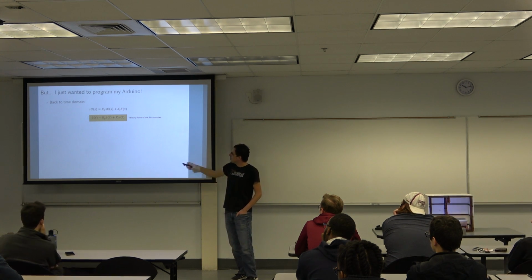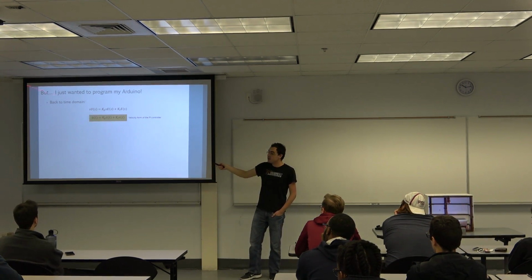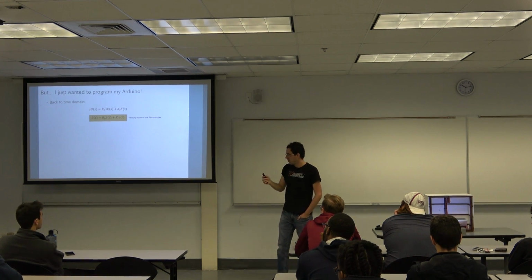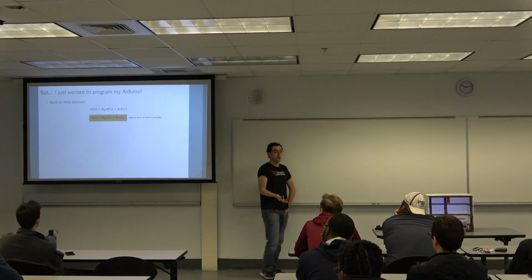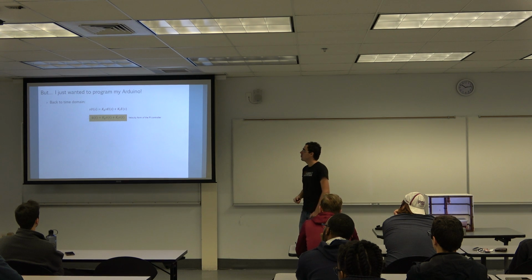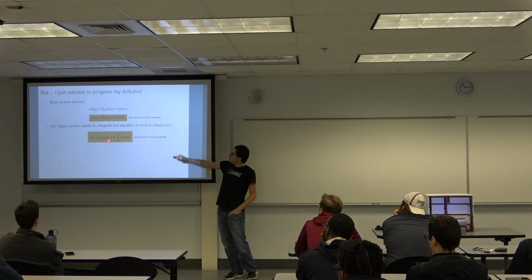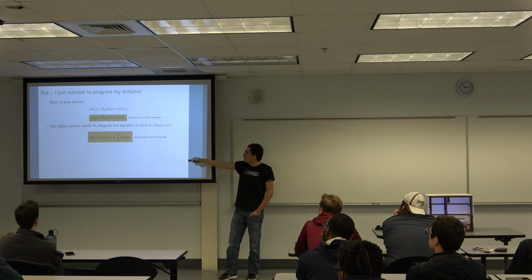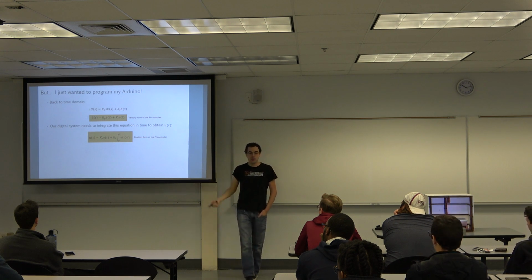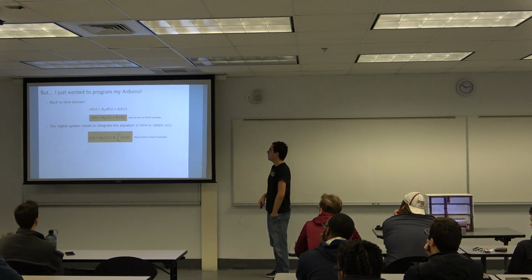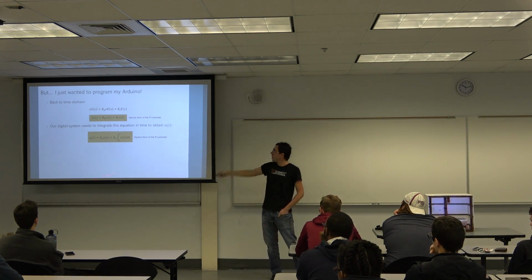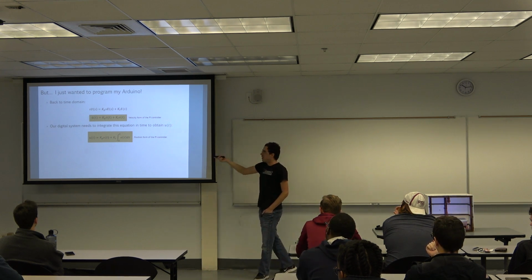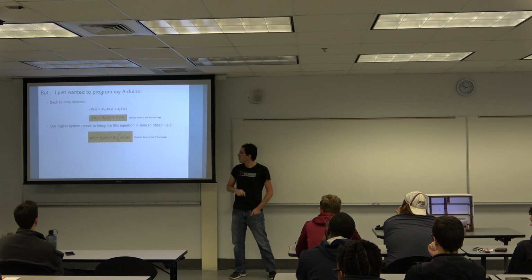And it computes the derivative of the control input. But most of the time we're not too interested in the derivative of the control input. We're actually interested in the control input itself. So we need to integrate this once. So we integrate U dot, and we get U. Integrate E dot, you get E. This E here we can't integrate, so we have to leave it in integral form with the dummy variable tau instead of t. And this is what's regarded in the literature as the position form of the PI control. It's just a distinction in how we compute it. It has the same behavior, the same characteristics.